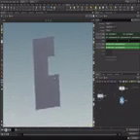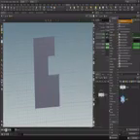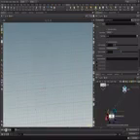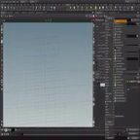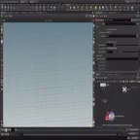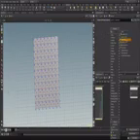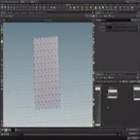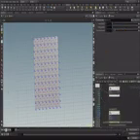And what we can do right now, if we want our original primitive to have this as subdivisions, is use the Voronoi fracture node. So let's get this Voronoi fracture, and we're going to wire in our primitive on the left. And the points we're going to wire into are not this grid, but are going to be the centroids of those primitives. So if I would be placing a point loop or VEX or whatever, you can select point, you can do the add point function, and go over there and remove prim. Let's remove the original primitive. There we go.